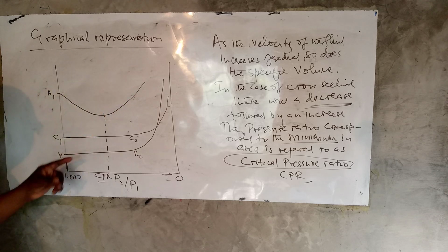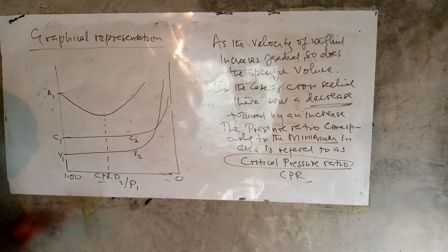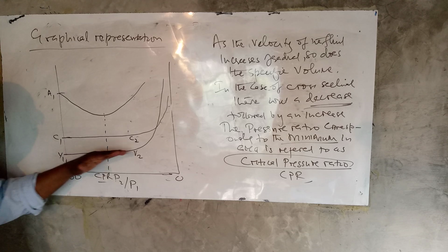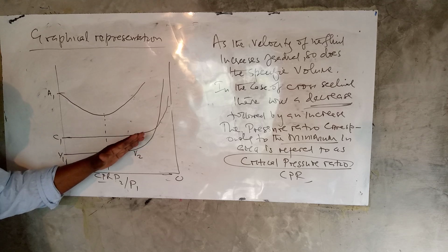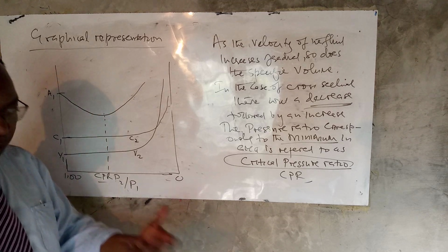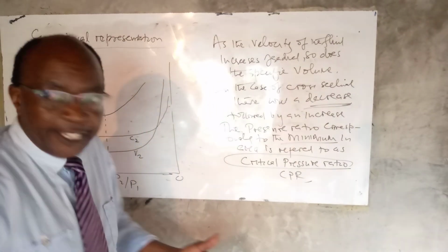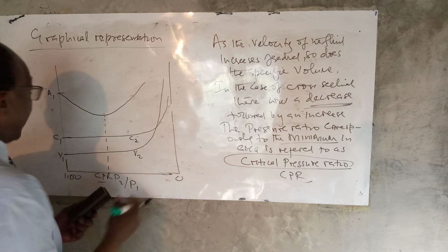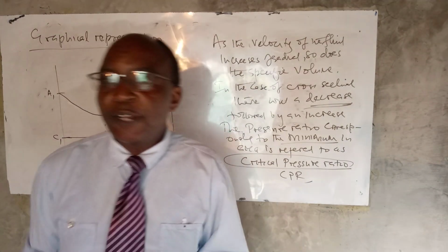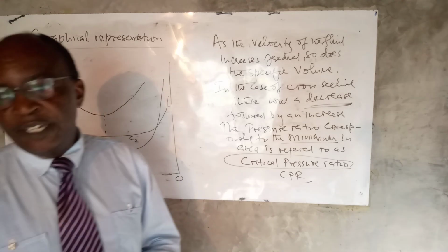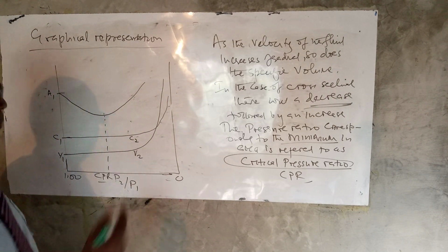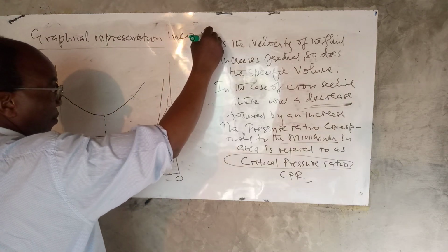And this decrease in area, if you look at that equation of continuity which we talked about, does make sense, because the specific volume increases gradually but increases steeply towards the end. And there are cases where, for ease of calculations, you can assume the specific volume is constant, and in that particular case, you are thinking of an incompressible fluid. That will make our calculations a lot easier.